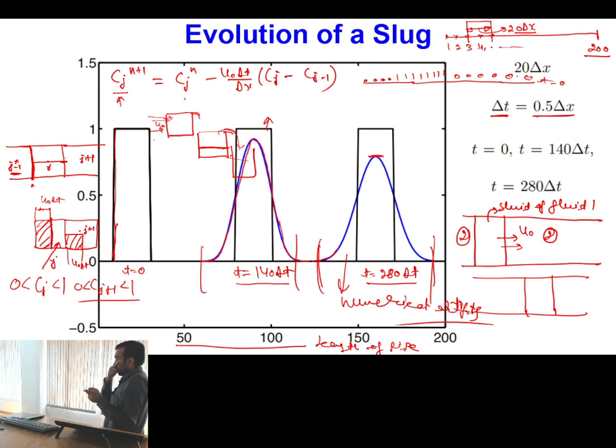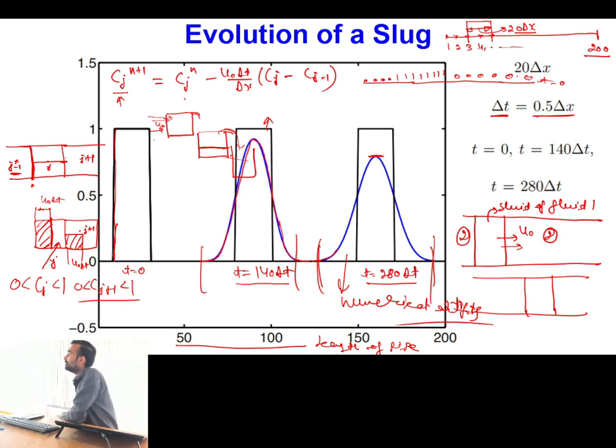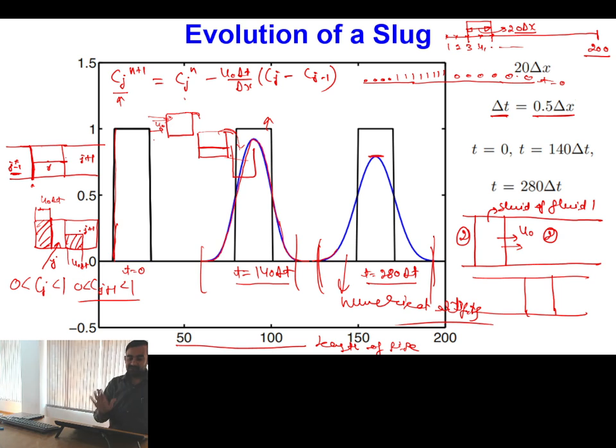But here, along with the momentum, we also have to tell how much portion of fluid 1 and how much portion of fluid 2 is moving across the boundary. So you can see that the use of the normal upwinding scheme, even for this simplistic approach involving so many assumptions and only one dimensional advection, results in a significant amount of numerical artifacts. Are all clear with this point?